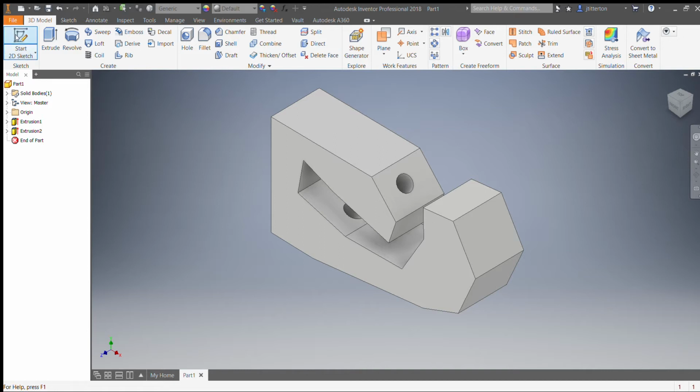All right, so if I wanted to start a new sketch, I click on there. If you are starting something new, click New, and always make sure it's English standard inch part for our purposes. If you're working in metric, you'd do it the other way. If you're making assemblies, standard inch part. All right, and we'll do all those another time. These are common problems that people have.